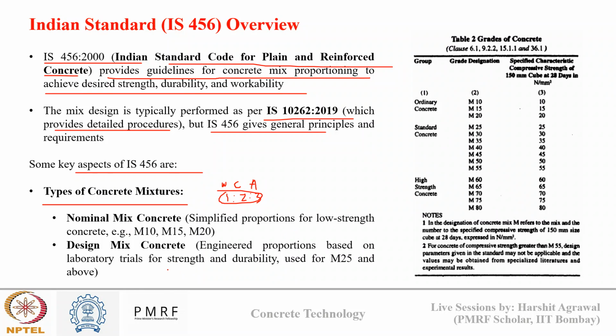Whereas design mix concrete is where we engineer the proportion of individual components through laboratory trials for a specific strength and durability requirement, and these are used for concrete having strength of M55 grade and above. Okay, so